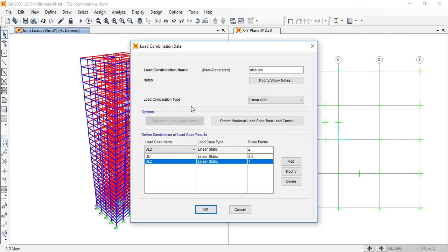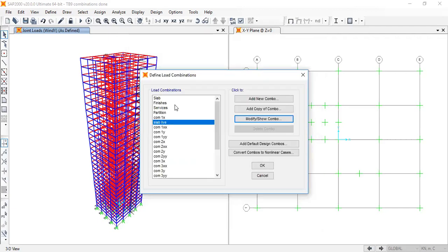So let's say you have a classroom where the seats can be removed. So you originally designed it for 2.5. Because at the end of the year people can dance, which will create a static and dynamic load both, so this 2.5 will be double when they jump and dance, right? So that will be 5 kilonewtons per meter square. That's why they usually use 5 kilonewtons. But there's another case also, I will show you what it is.